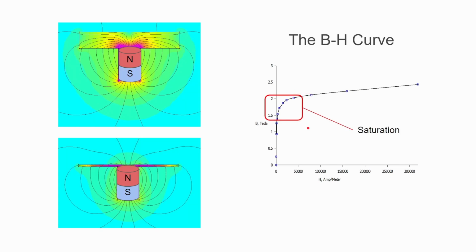So this is what's happening in the example below. The flux density in this area has gotten so high that the steel is saturated. Its permeability is decreased to the point where some of the field actually prefers to flow through the air now instead of the steel. This is a big departure from electronics. It's not like current in an electric circuit will just leave the wire and start going through the air at some point. The key difference is that electrical resistance is constant, but for ferrous materials in a magnetic circuit, this parameter depends on how much flux is flowing through the material.